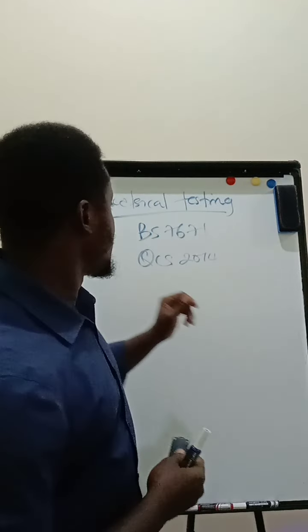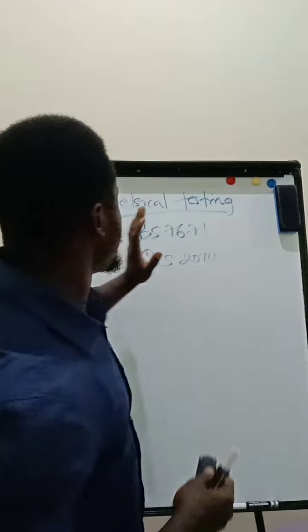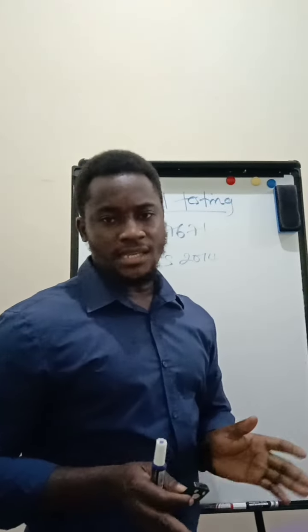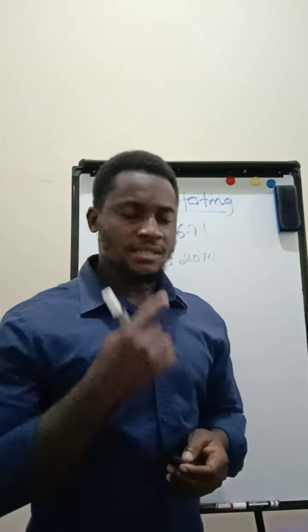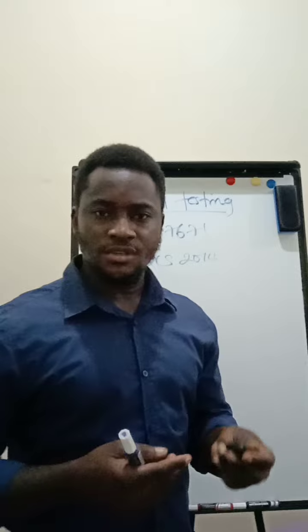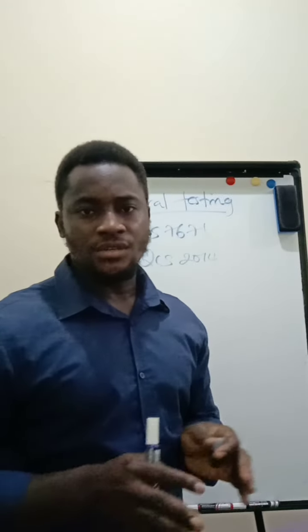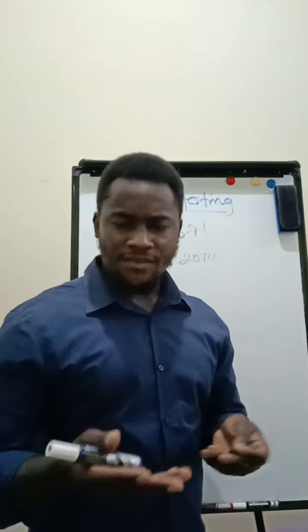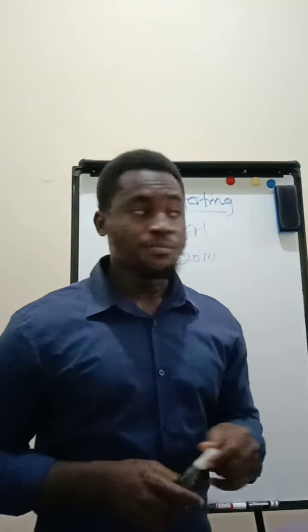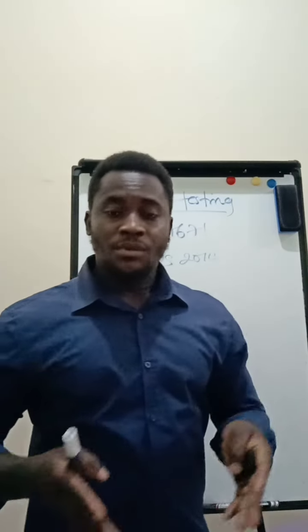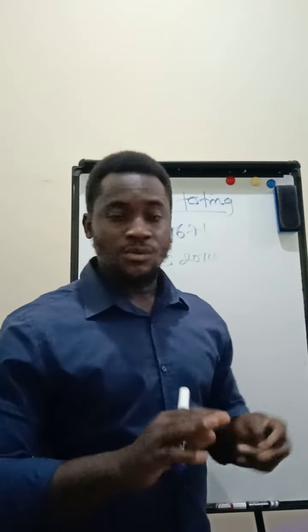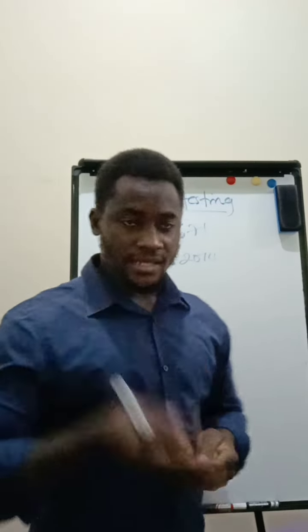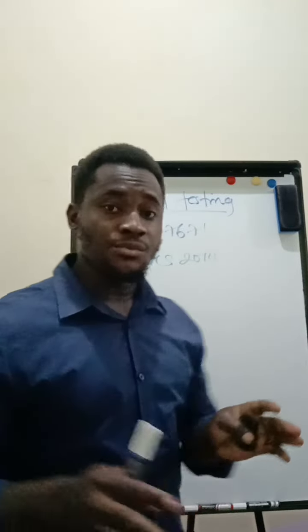So basically I'll be dividing this testing work into two different parts, which are the live test and the dead test. I'll start with the dead test. The dead test is a test which is carried out when electrical supply is not given to the installation. Supposing we have an electrical DB or an electrical panel board on which we have to carry out testing, the test that you'll be carrying out on this panel board when electricity is not supplied to it will be called the dead test. While when you supply electricity to this panel board, the test you'll be carrying out will be the live test.